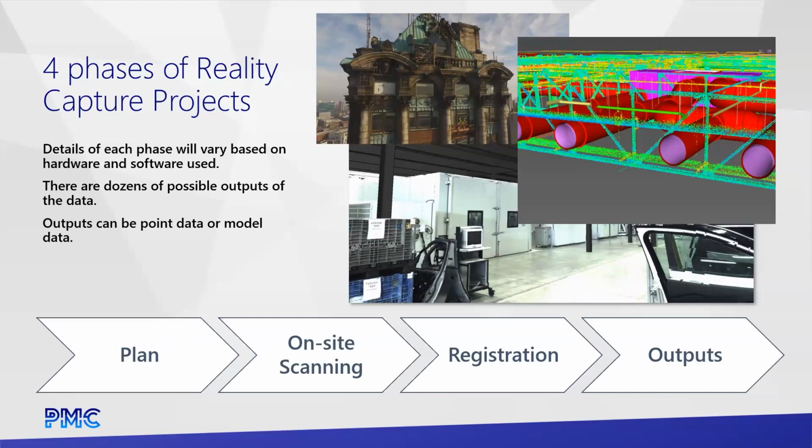Then there's another part that's going to happen with most of this work, which is the registration or the post-processing work. No matter what capture technique is used, there's almost always some post-processing. The only exception is on smaller jobs, 5,000 square feet and below. Those can be post-processed live on site, so when the operator leaves the site, the data can be ready to go. On projects any larger than that, there are complications that usually mean you can't do the on-site post-processing.